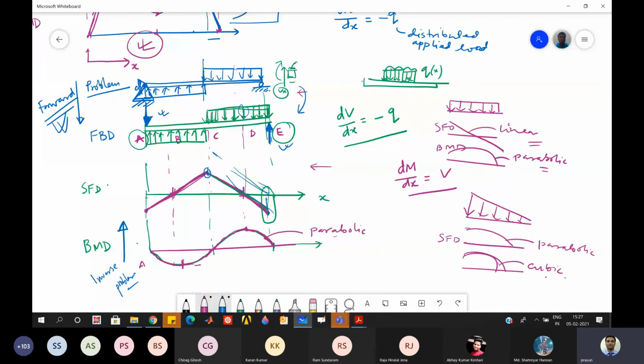So this load, the total load times the distance, half of this distance, and then this E force times the distance to that force, and you have to take the sense, clockwise or anti-clockwise, and you will find this point. So directly you can locate this point, and you know from this force what this point is, and then draw the straight line. So this is the complete diagram of this one. And then you know this force, so you show it here. You can see only by finding a moment about this point, I can draw the SFD, right?